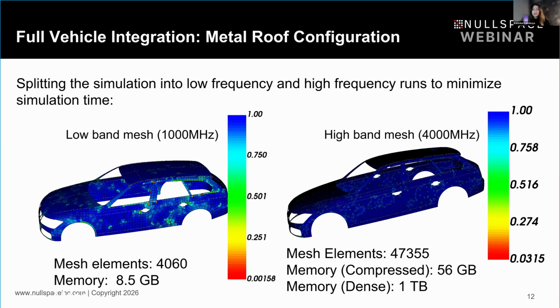Like I split my simulation into two parts. So I simulate separately. It's the same model, right? But I simulate separately the low band and the high band. That is maybe very niche knowledge that maybe only people who work with these wideband antennas know. But you really need to do this to not have an empty mesh that you don't need, for example, for the low band.